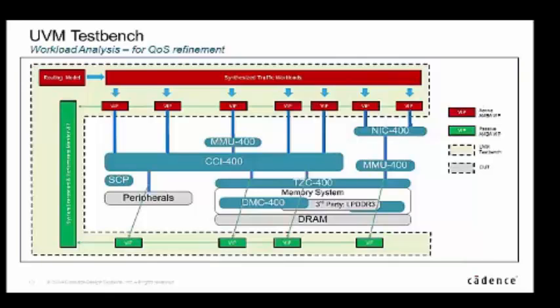Is this automated, the DDR efficiency tests? Yeah, that's the idea, we'll automate them. Obviously we have a DDR controller, so we're testing it on ours as well as ARM's. If you look at the way DDR is configured, you have your address, and I map the row, column, banks, and each DDR has lots of different configurations. Once you've specified that, we can automate the generation of the tests for you to do continuous row hits or row misses, bank hits, bank misses, all of that. It's very easy, it's just address generation.